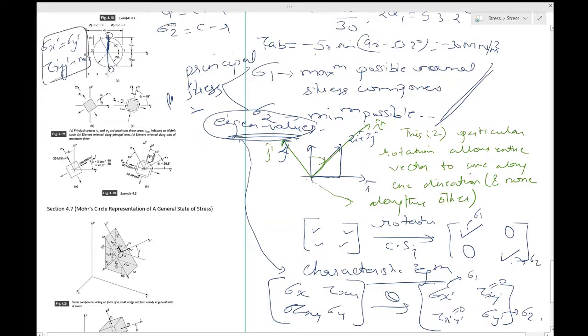So this is also another interesting case, and in this case, obviously, R is your tau max, and sigma D is equal to sigma E equal to C. Okay, this value. D is the axis of maximum shear. This is the axis of maximum shear. This is the principal axis. And these are the principal values.